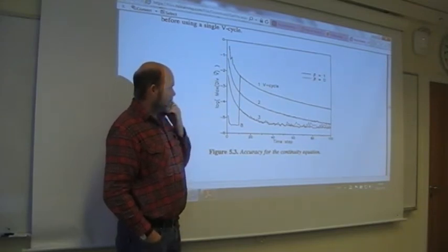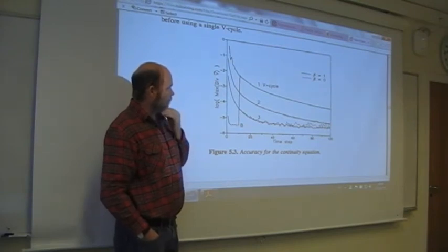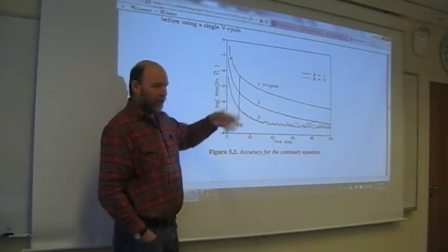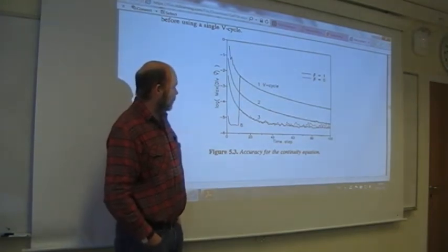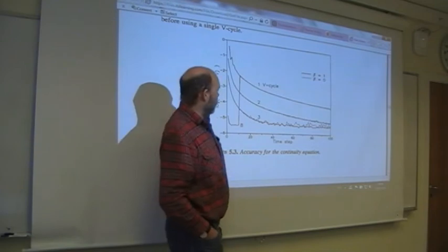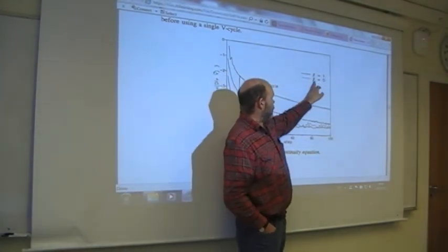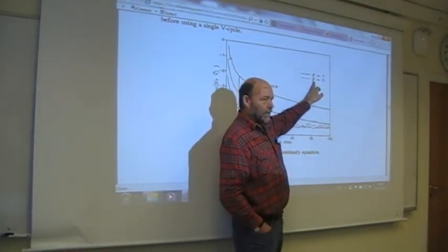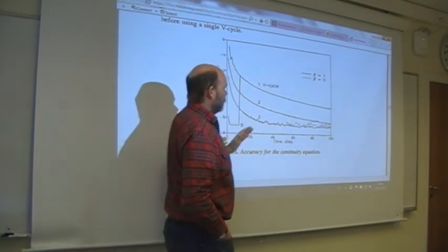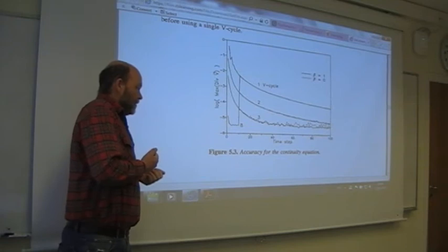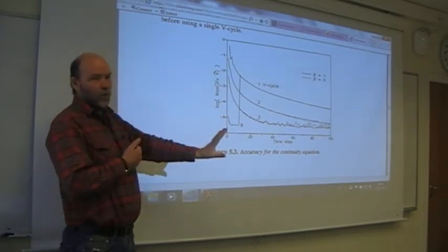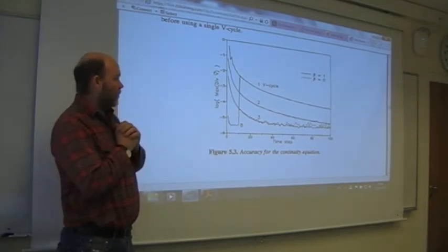So that's the nice thing with the projection method in SOLA. You can do some physics with the criterion, not just using a residual or something. Also here I played around using the switch, if you can remember this one, the beta. That was in the split step method. When you calculate the tentative velocity field, you normally will use the old pressure, the pressure from the previous time step.